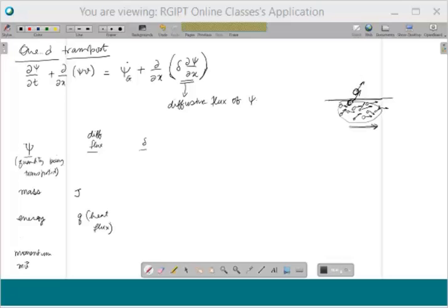So momentum transported across this surface, which is like force experienced by this part due to this part, need not be in this direction. It can have components in this direction and this direction. Therefore, due to this randomness, the momentum transported per unit time per unit area across this surface can actually have three independent components. One could be parallel to the velocity direction, and two would be perpendicular to the velocity direction.